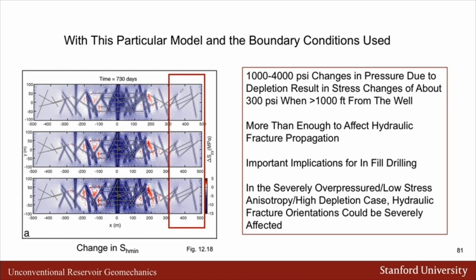And so this change in SH min that we see out here would result, a 1 to 4,000 psi change in pressure due to depletion would change the least principal stress on the order of a few hundred psi within 1,000 feet of the well. This is more than enough to affect hydraulic fracture propagation and has important implications for infill drilling.